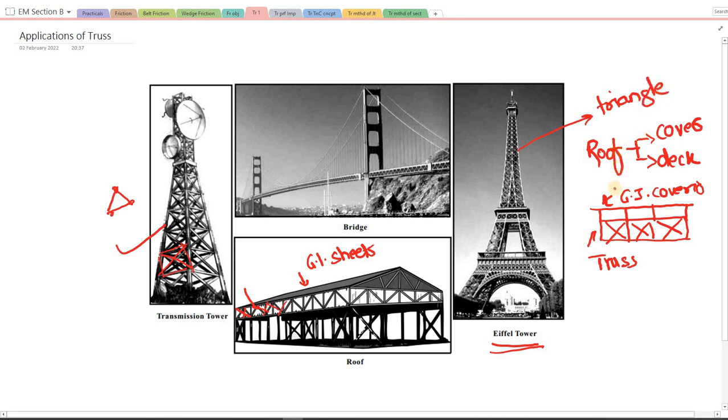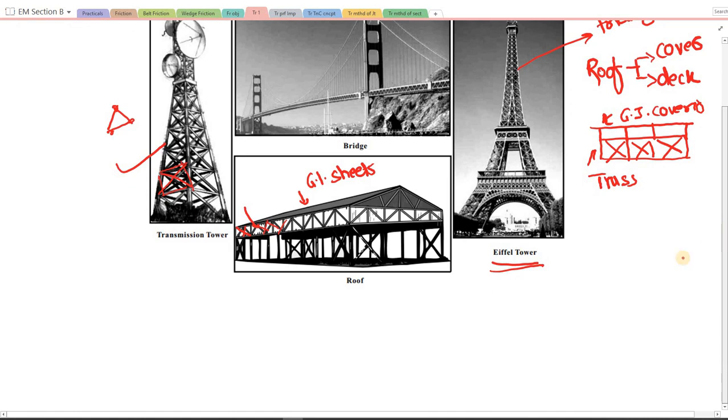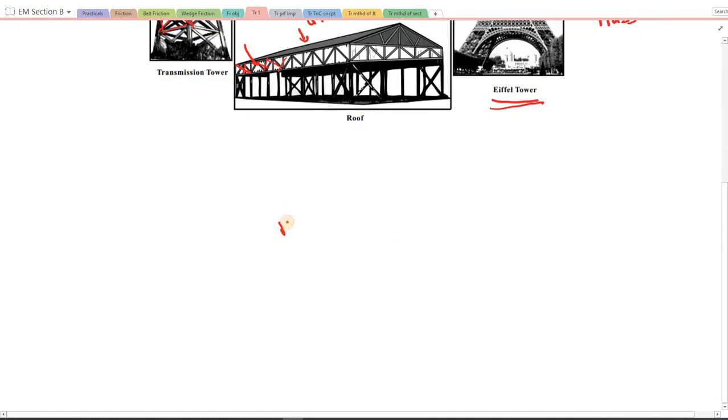So this is our theoretical take on the concept of truss. In the next lecture we will be looking at the types of truss, based on whether it is a perfect truss or an imperfect truss. When we differentiate whether a truss is perfect or imperfect, we have to look at a formula, which is m = 2j - r, where m is the number of members. Let's write it down. m = 2j - r. This equation is the sole deciding factor to judge whether the truss is statically determinate or not, whether we can determine the loads or type of load in the truss or not.